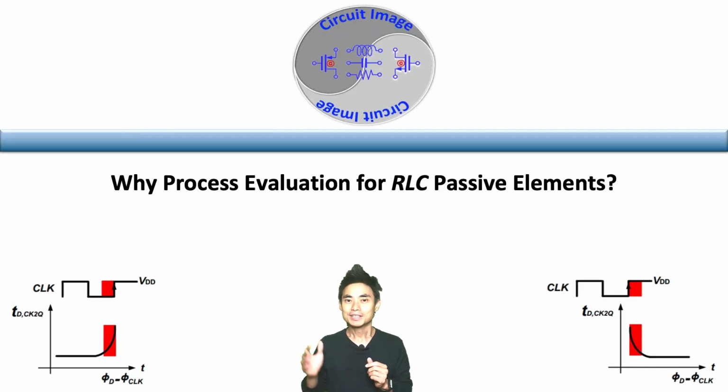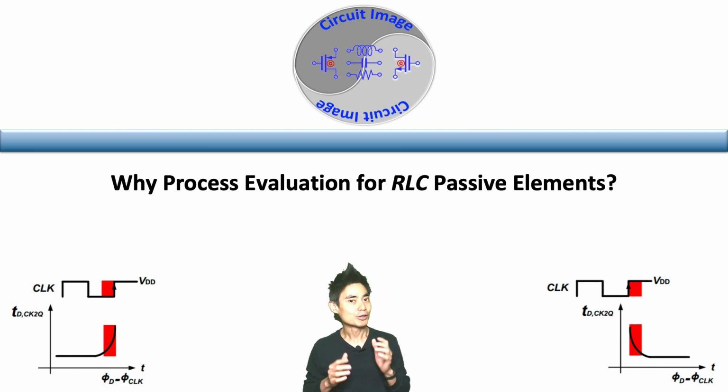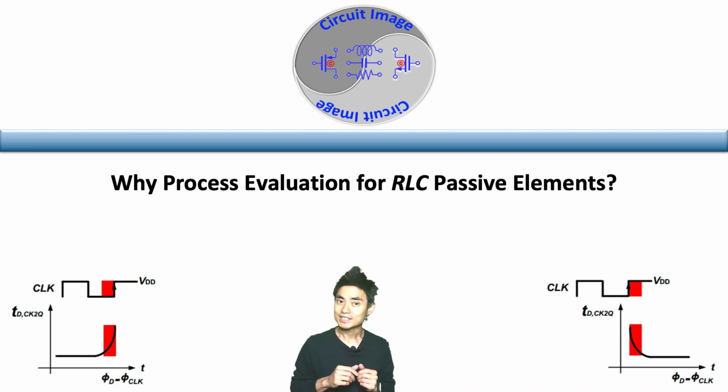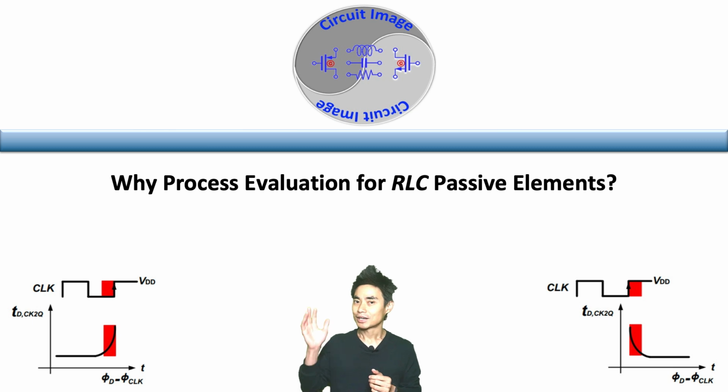We know the benchmarking or evaluation of flip-flop setup and hold time is very important in digital timing. In addition, the gate characteristics are so different over different technologies or processes. Therefore, we must exercise the flops characterization every time in any different process node.